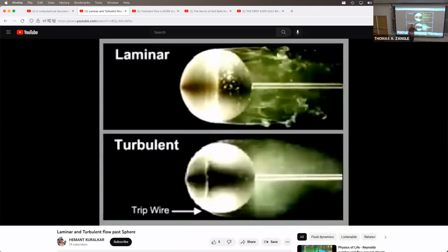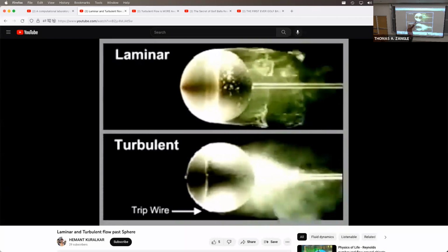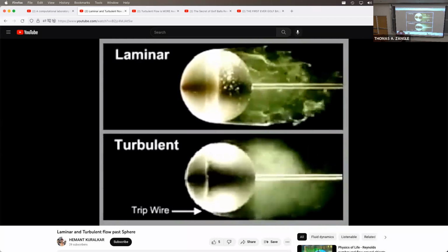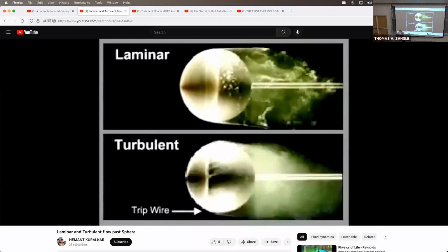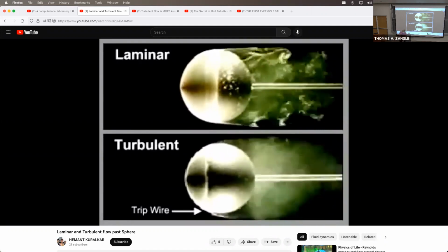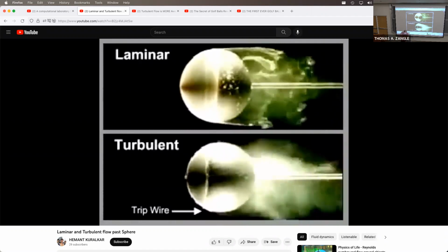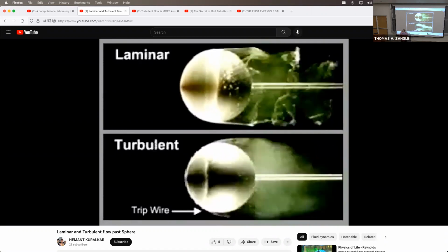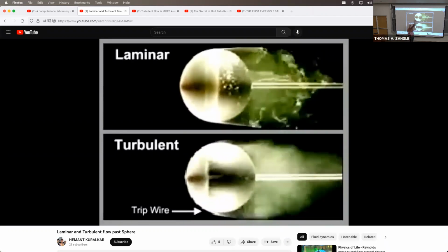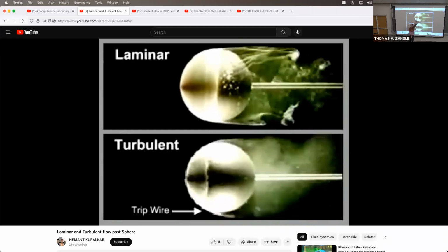force on those objects. The first is what we call the shear drag, which is basically the drag of high speed flow moving over low speed flow or zero speed flow. And so you have some shear force to actually drag that fluid from over at high speed over the plate where there's no slip condition. That's what dominates here, right? That's what's driving the drag over a flat plate. And that's what's driving the drag where we have this attached boundary layer.